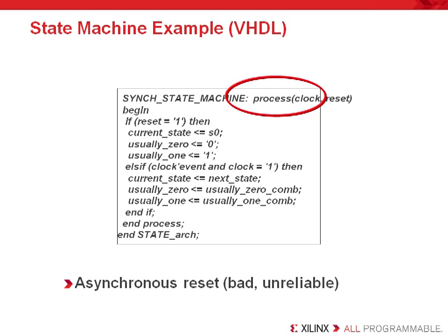This is the synchronous portion of the finite state machine. Note that with this construction, the outputs are also registered. While this is perfect to register the outputs, in essence effectively pipelining an output stage, note that the reset signal is asynchronous. So not a good idea to build it asynchronously. You'll need to recode this to make it synchronous to assure it will operate. But again, adding the register stage rather than leaving it purely combinatorial is very good, as we'll learn more when we get into the pipelining discussion.